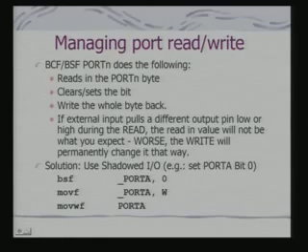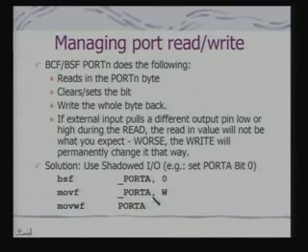So this also can be a source of problem and a source of error when you are interfacing external devices via a port. One of the solutions is to use what is called shadowed I/O. That means you clear, in this case, basically when I am showing underscore port A, it is not that I am writing onto exactly the port A memory location, but a copy of the port A memory location, which is in the general purpose set of registers which the PIC provides.